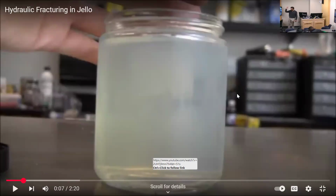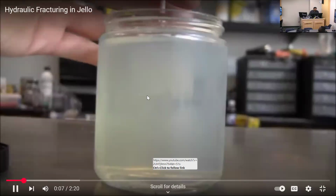Then she's gonna take the straw out and go deeper, go back in again, much deeper, where the overburden would be higher than the confining stresses, and try to make a fracture there, and then the fracture is gonna look different. It's gonna look more axial to the well. The width would be perpendicular to the well. Yeah, you will see. You will understand when I show it.